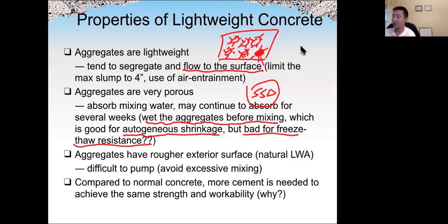The third point, aggregate has a rougher external surface, especially pumice and other natural lightweight aggregate. This makes lightweight concrete harder to pump. So we need to modify the mix design a little bit, such as increasing the paste amount to compensate for that.